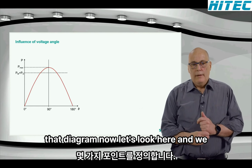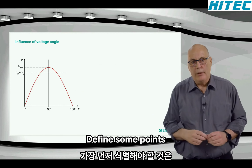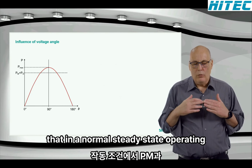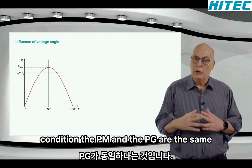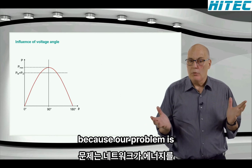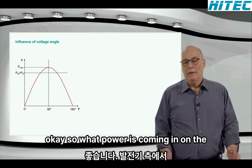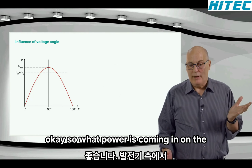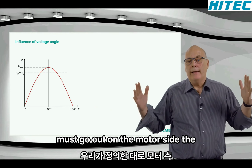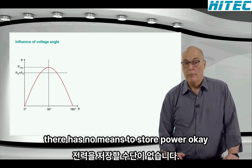So let's look at that diagram now, and we define some points. The first thing we have to identify is that in a normal steady state operating condition, the PM and the PG are the same, because the network does not store any energy. So what power is coming in on the generator side into the electrical system must go out on the motor side. The electrical system, as we have defined it there, has no means to store power.